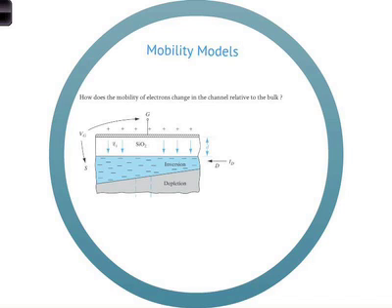Why? Because we talked before, the electrons are pulled up towards the interface. So more electrons see the interface, more electrons scatter, you expect the mobility to decrease. So it's a very different effect. But the implications are very similar. Okay?